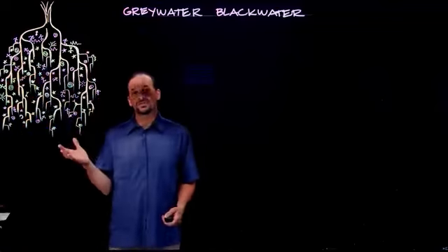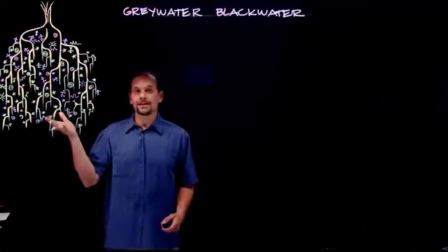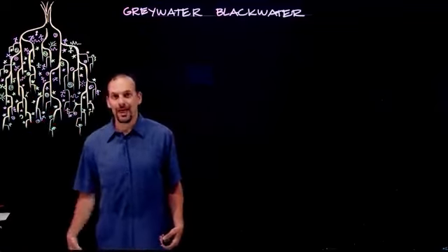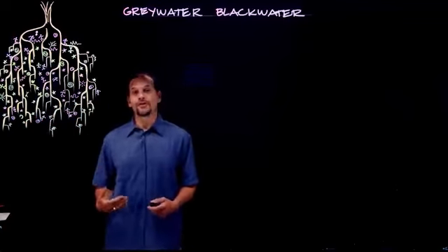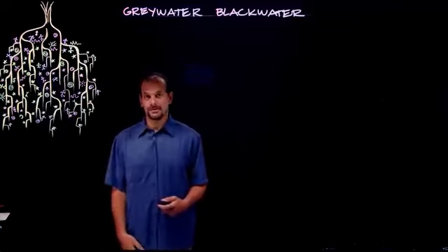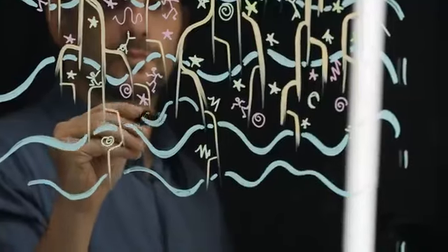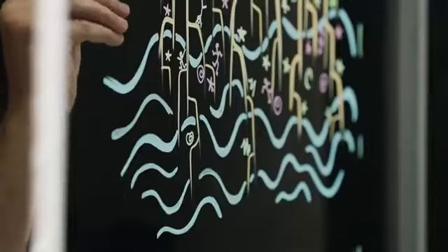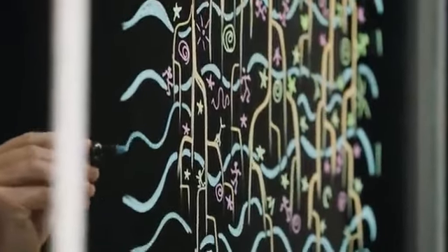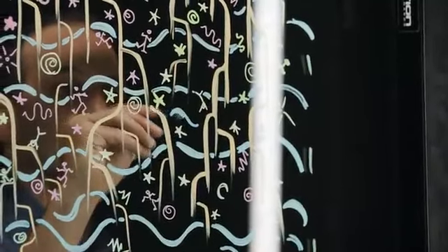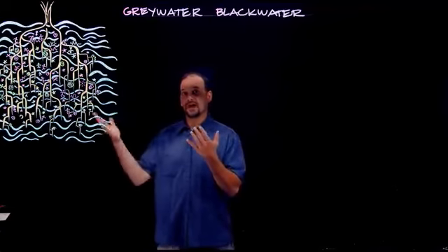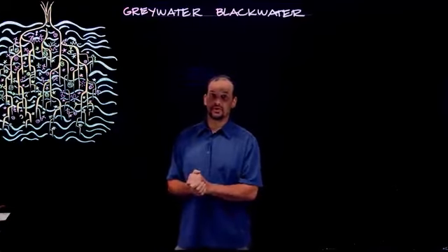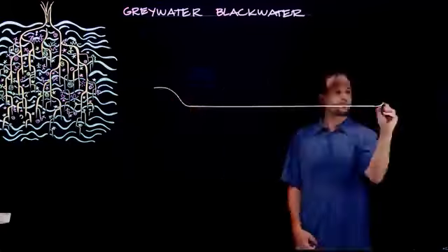In addition to this root filter, some wetland plants can actually absorb heavy metals from the water up into their tissues. So the goal of any wetland water treatment system is to create the maximum amount of contact between the dirty water and the roots of a diversity of plant species. The very simplest version of how this concept is used in wastewater treatment is the constructed wetland.